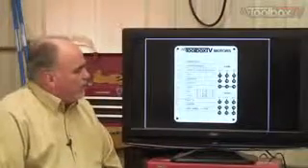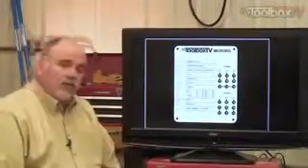Motor nameplate data is critically important when you're doing maintenance work or electrical installation work. The motor nameplate has all the information about this motor, and the nameplate we've used as an example is for a three-phase induction motor. It's dual voltage, 230/460 volt, and it's a 10 horsepower. Pretty common motor, and even though we made up the nameplate, MyToolboxTV doesn't actually make motors, the numbers are actually real from a real motor.